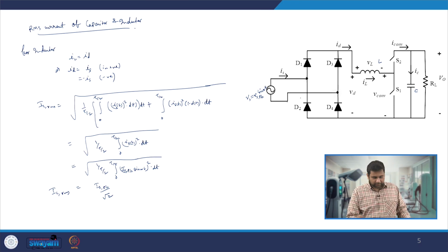So accordingly, depending upon this RMS current, because we already know Is peak, how one can calculate Is peak. Generally in the specification PL is already given. So from this PL one can calculate P in, which is nothing but PL by efficiency of the converter. We can assume an efficiency and then easily calculate how much power needs to be drawn from the input.